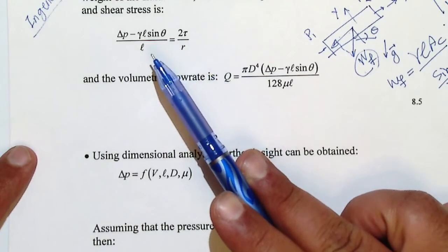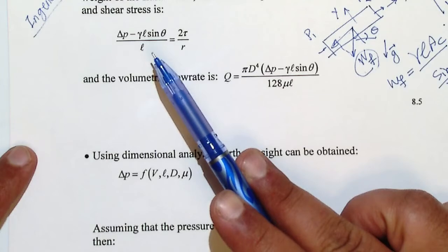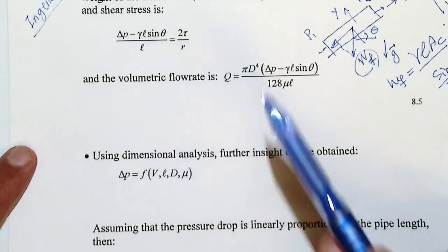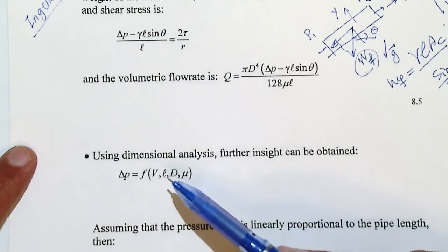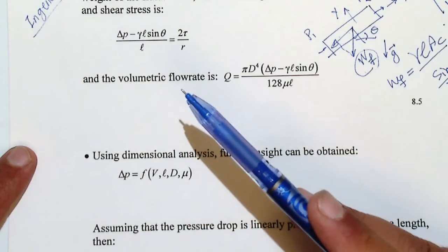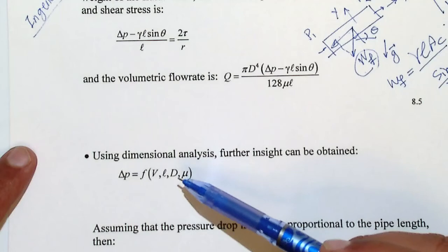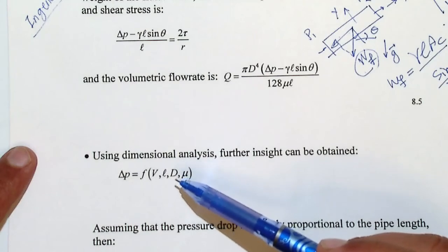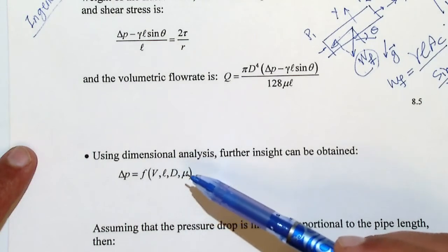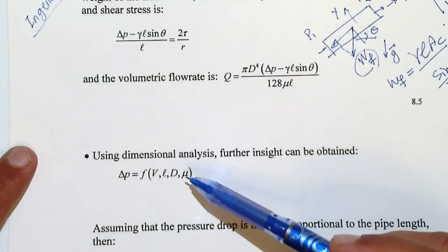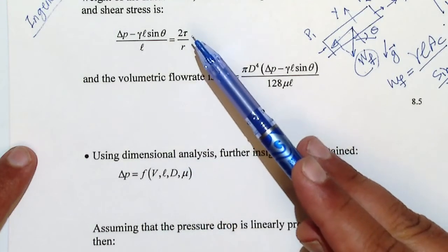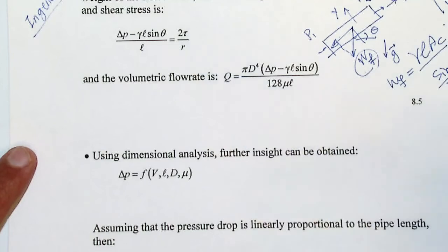In the equation you will find out that it's related to L, the length of the pipe, and also D shows up here because of the area, so it's going to be different with different D, because of the Reynolds number, right? And also because of mu, and mu is going to be inside of tau, right? These are all the terms that could affect your delta P.